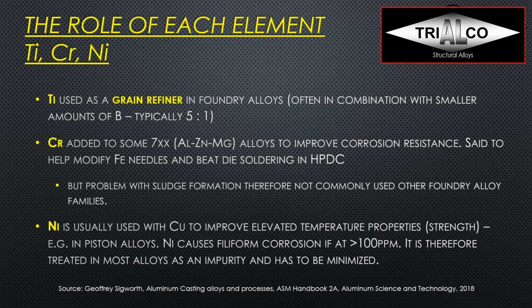But watch out, nickel is causing filiform corrosion, so the corrosion that goes deep into the casting, and that already happens if it gets above 100 ppm, so at a very low level. So it's therefore treated in most alloys as an impurity and has to be minimized.